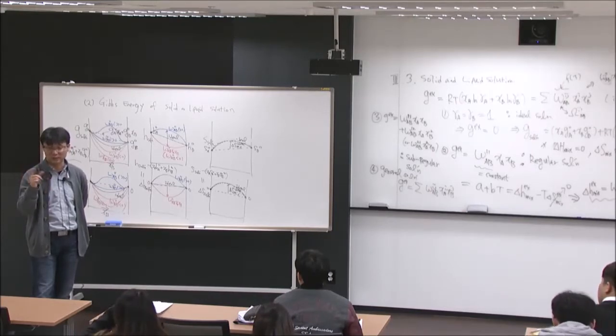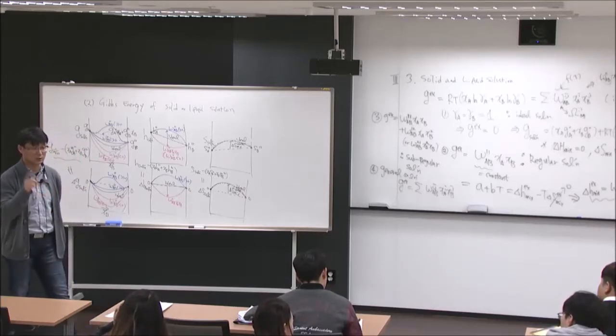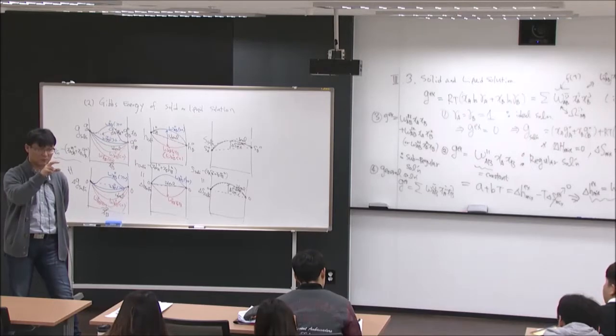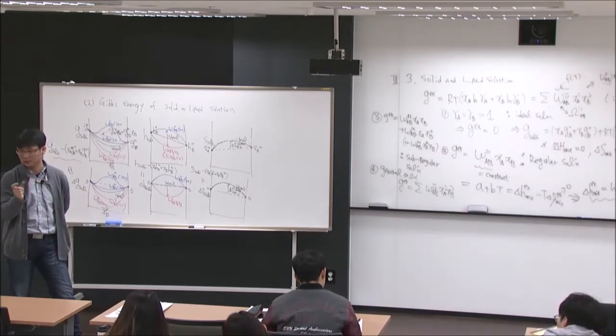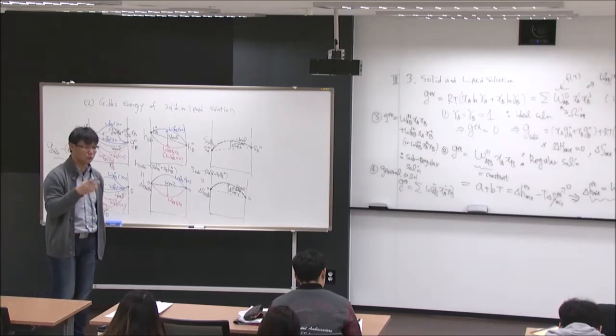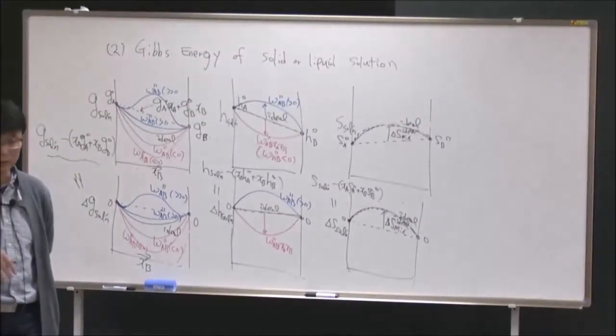That's what we call a real gas. And in that case, we theoretically have to use fugacity instead of the partial pressure, which considers the interaction between the gas species, okay. But in most cases, 99.9% of cases, we don't have to consider it that way. We can just assume that everything is an ideal solution, okay.